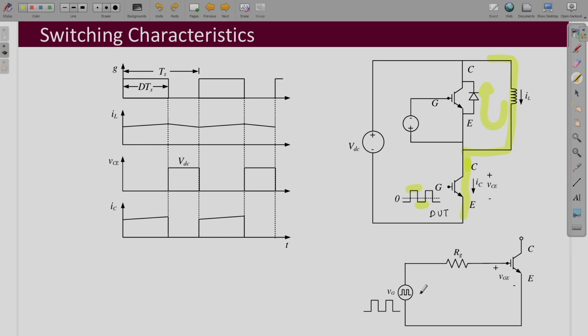What we do here is, there is a driver circuit which we can represent as a pulsed voltage source, which is giving your VG pulses, and the maximum it provides is capital VG, and some negative voltage is also provided. In between there is a gate resistor RG, and through that the gate emitter region gets charged and discharged. This part is your gate emitter voltage VGE, which we will see how it changes as turn on and turn off happens.